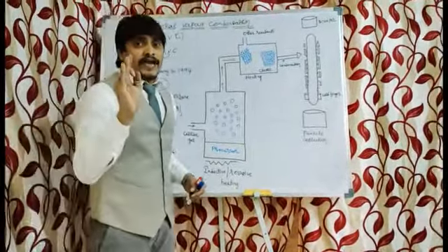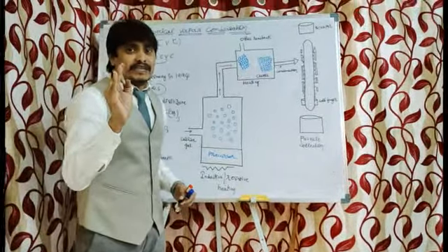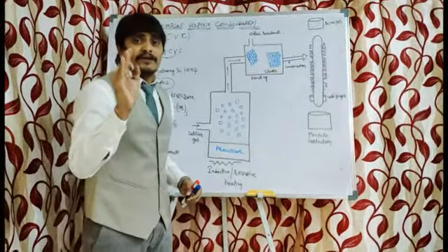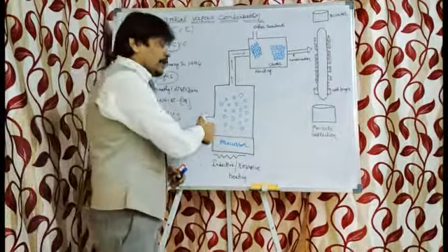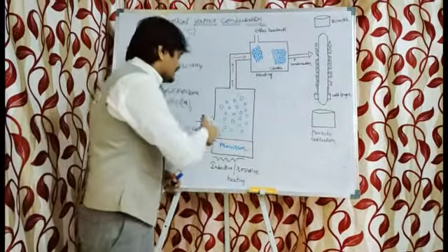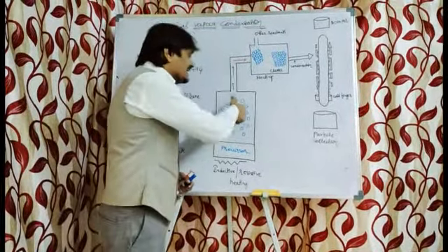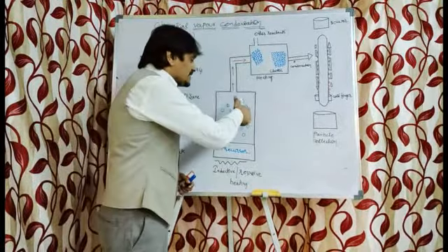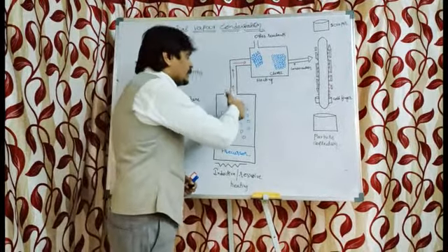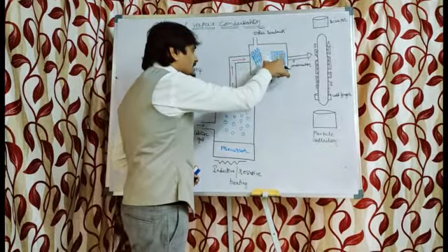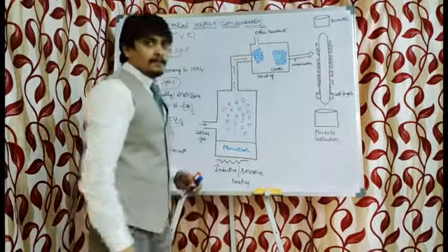And what are the carrier gases? Already I have explained in the previous class also: helium, argon and krypton. So what is the purpose of the carrier gas? This carrier gas carries the vaporized precursor molecules into the chamber where the condensation process takes place.